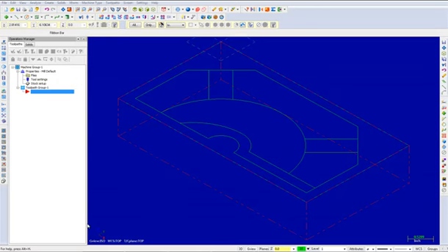In this video, I will show you a 2D high-speed dynamic core mill toolpath. 2D high-speed dynamic core mill utilizes the entire flute length of their cutting tools to produce the smoothest, most efficient tool motion for high-speed pocketing and core milling. The dynamic core toolpath machines open pocket shapes or standing core shapes using the outmost chain as the stock boundary. The tool moves freely outside of this area. The inner chain defines the limit of the toolpath.